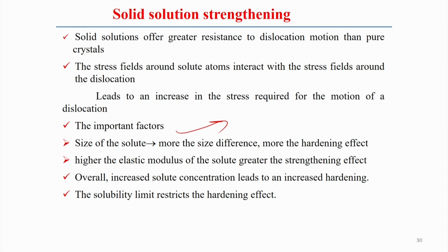So the concentration of the solute atoms in the solid solution is finally the most impactful in deciding the hardening effect on a specific solid solution. But this hardening effect is limited by the solubility limit of a specific solute atom in the solution. So these are the overall facts related to solid solution strengthening.